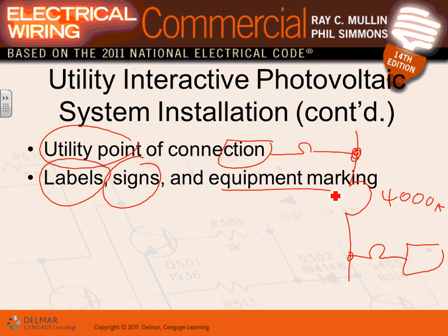And in 2014, Adam, they introduced emergency shut-off. They want to have a push button like this. That was in 2014, when you can slam the push button and it shuts down all these panels. So you have a little relay with every panel. It shuts down every single panel.